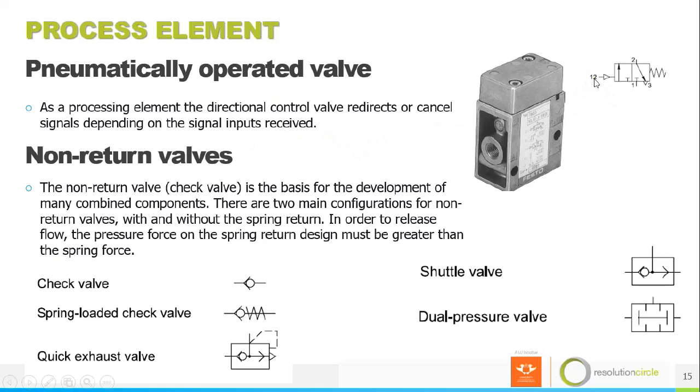So at port 12, I will receive a pneumatic signal. Whenever this valve receives a pneumatic signal, it will change its position from this position to this position. We have non-return valves. Non-return valves, or check valves, are the basis of the development of many combined components.